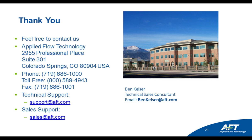Well, the software that I was demonstrating today and showing screenshots of is called AFT Fathom, and that is specifically designed for modeling incompressible flow for liquid piping systems. So it does have the ability to model low velocity gases that has small pressure losses and no temperature change, but it's going to be using incompressible flow methods.